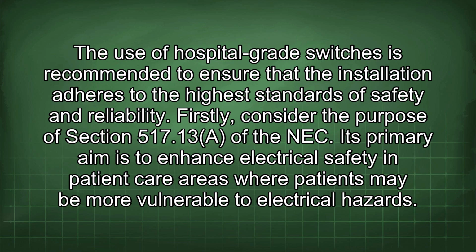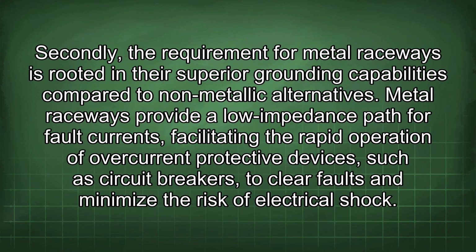Firstly, consider the purpose of Section 517.13 of the NEC. Its primary aim is to enhance electrical safety in patient care areas where patients may be more vulnerable to electrical hazards. Secondly, the requirement for metal raceways is rooted in their superior grounding capabilities compared to non-metallic alternatives. Metal raceways provide a lower impedance path for fault currents, facilitating the rapid operation of overcurrent protective devices, such as circuit breakers, to clear faults and minimize the risk of electrical shock.